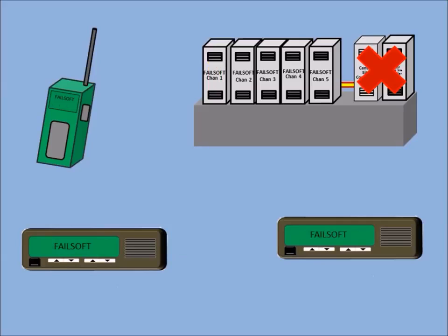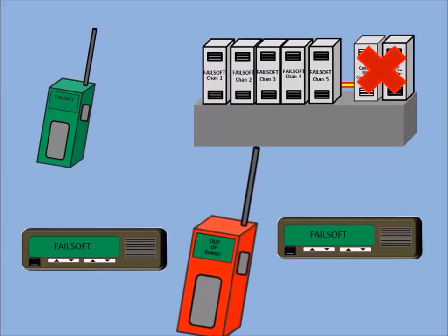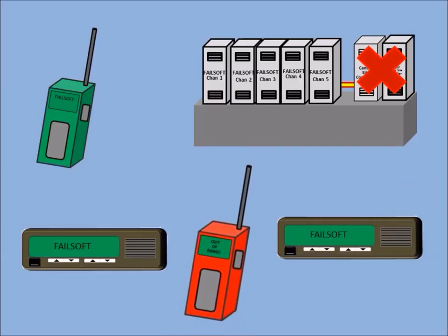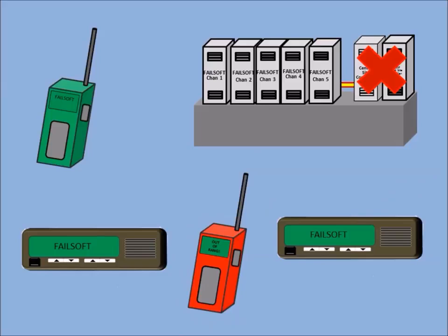Subscribers do not need to operate in failsoft. If you have a large number of users and some of them perform tasks that are less critical, these users can be configured to not operate in failsoft, leaving the higher priority users to operate on the failsoft channels. This reduces the on-channel congestion that would occur if many groups operated on that one channel.